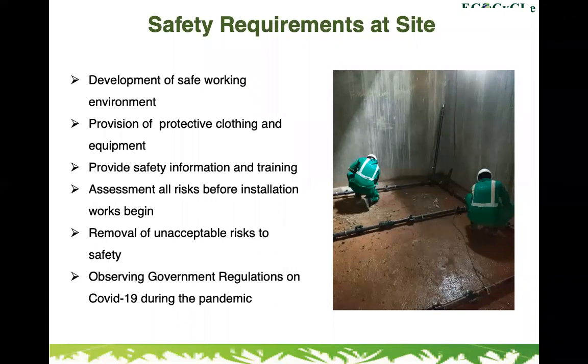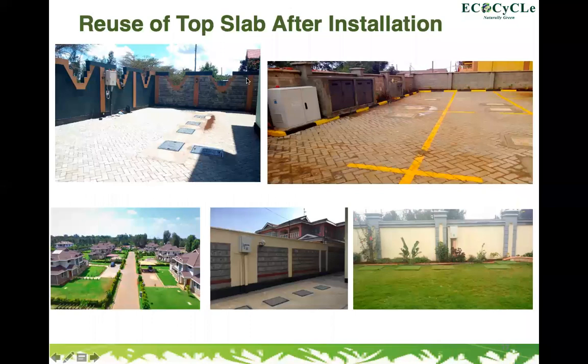And for us to convert your existing septic tank or conservancy, it also has to be confirmed that it is watertight and doesn't allow groundwater or stormwater to leak in, because the only sewage that we treat should be the sewage coming from the house, because we design it based on the expected peak occupancy of a premise. Thank you. So I will move to the next.